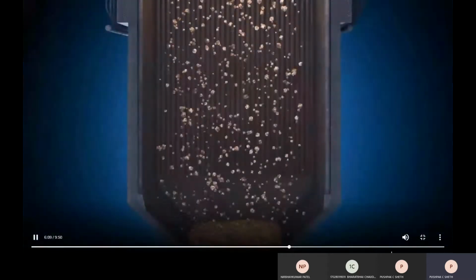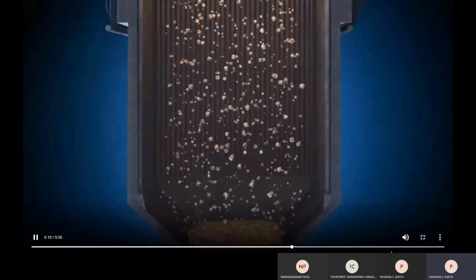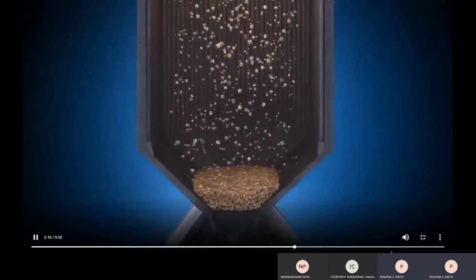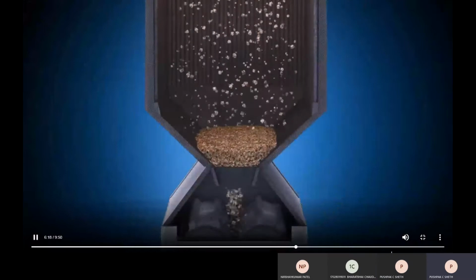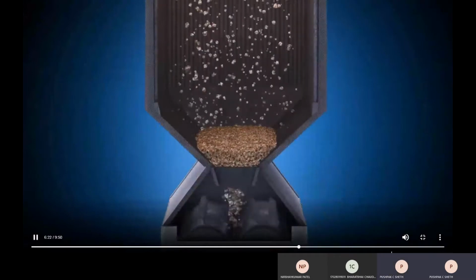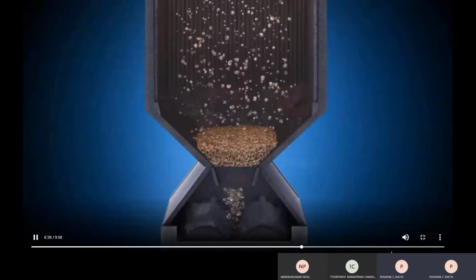Once combustion is complete, the heavier particles of ash, called bottom ash, fall into the bottom of the boiler. There, the bottom ash is crushed using clinker grinders, mixed with water and sluiced to the hydro bins. The water is decanted and the ash collected in dump trucks and either sold or moved to on-site storage.